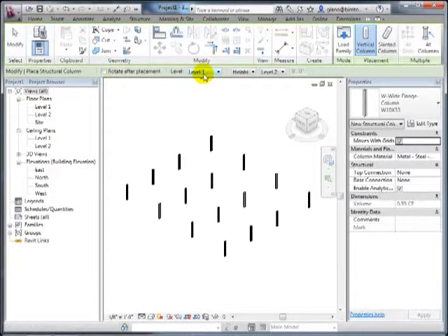It's this notion over here as to whether your beams are going to go up to a height or down to a depth. And this just has to do, watch out for this. In our architectural drawings, as we're looking at level 1, we tend to be drawing on level 1 and thinking about things that are coming up from the floor. Structural engineers sometimes look at it a little bit differently. They'll look at level 1 and they want to see exactly what's happening down. So, you have to watch out for this choice as to whether you're going up or whether you're going down. In this case, I'd already had it set up to height, so they went up.